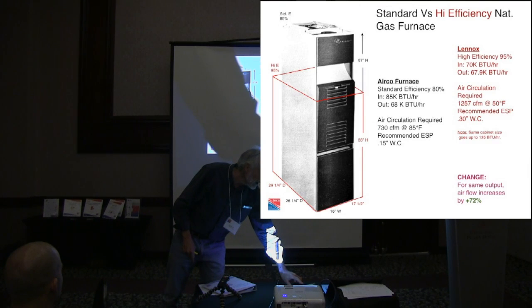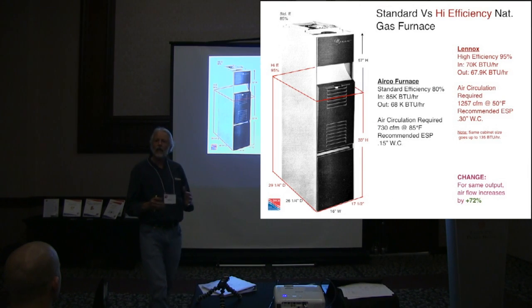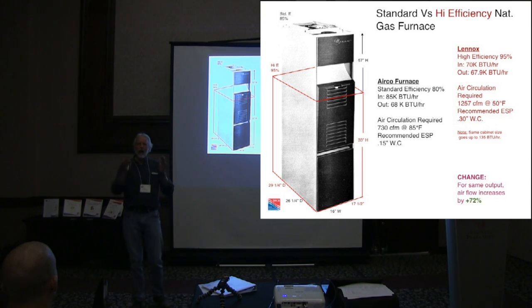The principles of moving air is to try to give you some understanding of how air moves through a duct. Because a ductwork system is real simple. You buy a fan, it moves air. But then against that, you've got to subtract the pressure drop, the static pressure drop incurred by the duct system, the filters, the coils, and the other things you may wish to add on. So it's simply you're buying something to move air, and then you're throwing a whole bunch of impediments into that duct system that slow it down. This is becoming serious today because the new appliances move more air.